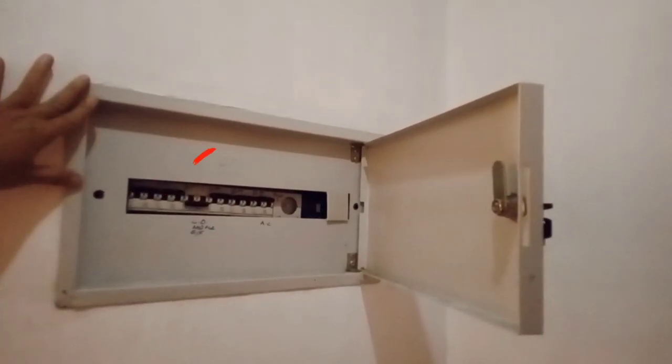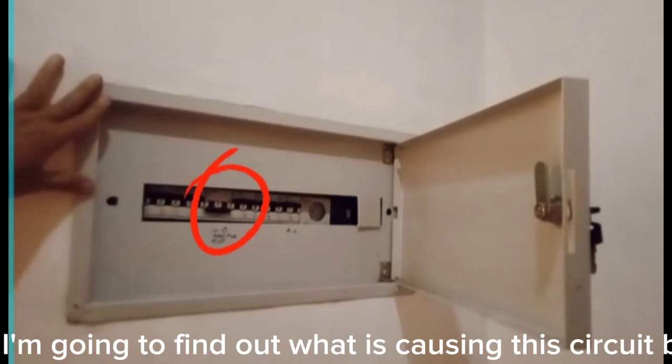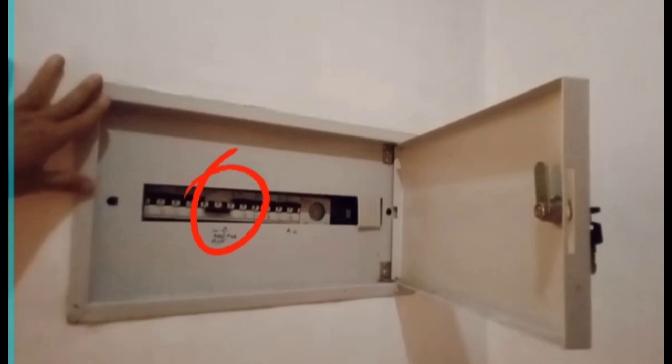This branch circuit breaker is tripping. I'm going to find out what is causing this circuit breaker to trip off. The first thing to do is analyze the problem and make a root cause analysis before attempting to open the dead front panel door.